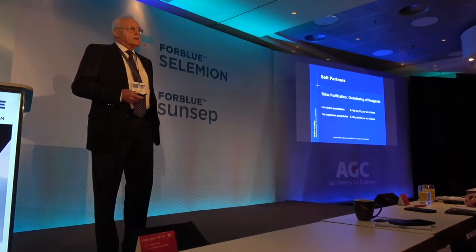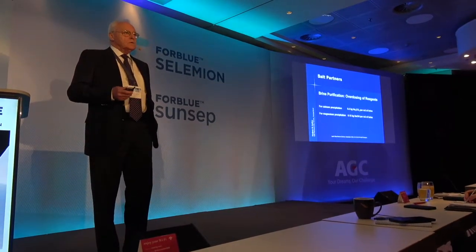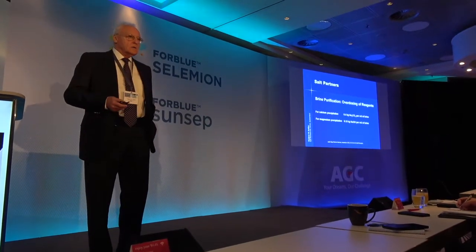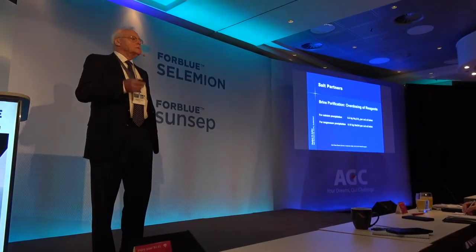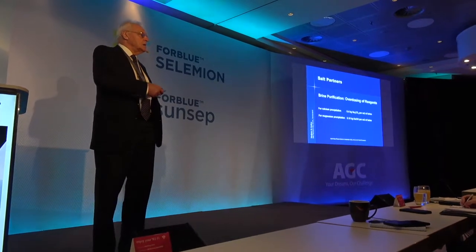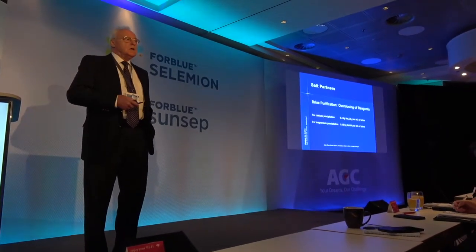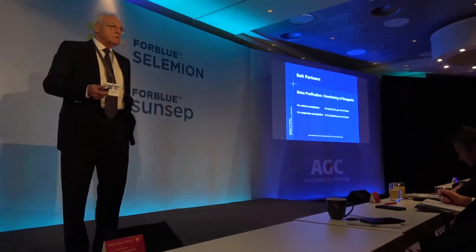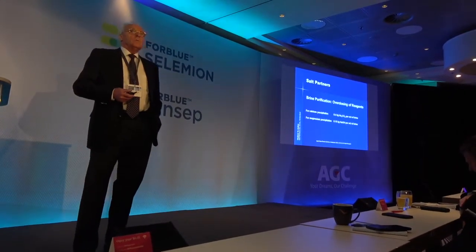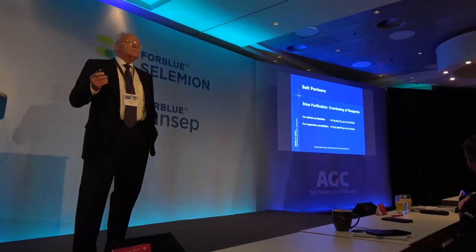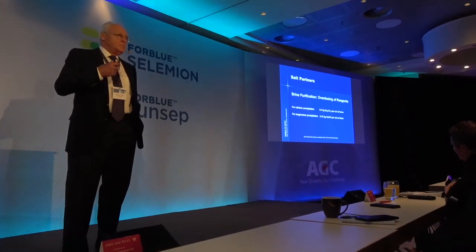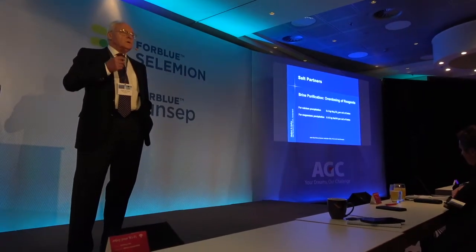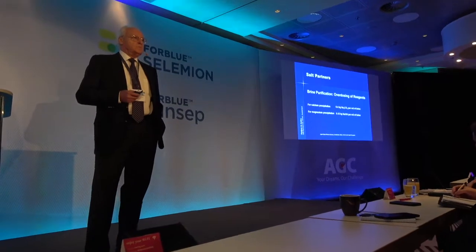Now, when the quality of the salt coming into the brine purification plant is varying, if the calcium is sometimes 0.1%, sometimes 0.2%, and sometimes 0.01% also, it is very difficult to maintain the overdoses of the chemicals in such a way that even the peak will be precipitated.